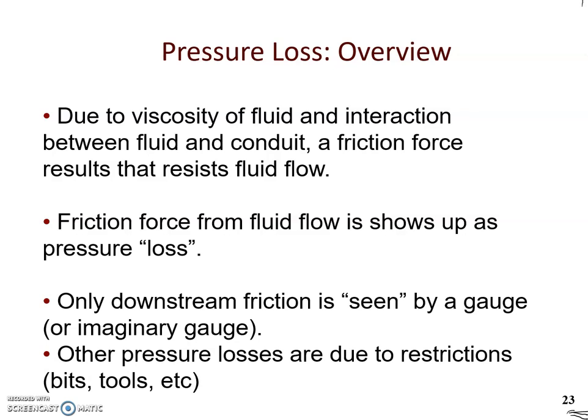This pressure loss of the fluid is important for us because, for example, you want to select a drilling fluid pump to inject the drilling fluid inside the wellbore, right? You need to know how much pressure you need in order to inject the drilling fluid through the drill pipe, passing through the annulus to the surface, and have some specific pressure at the surface, or at least it reaches the surface, right? These pressure calculations therefore are important to understand at what portion of the wellbore we have what pressure.